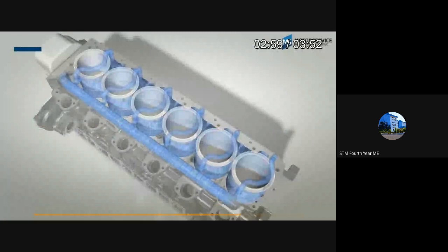Here is the water coolant, where the water will be flowing inside the engine. This is the oil. At the bottom of the crankcase, you can see the oil sump, a case where oil is stored inside the engine. These are the oil traveling pathways, and you can see how the oil travels to the connecting rod points, the crankshaft, and even the camshaft. You can see the camshaft lines here, and it even goes upwards into the engine head portion. So this is how the oil is moving.